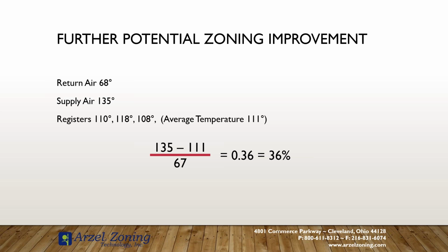And it seemed like such a simple thing to me that it really ties in well with zoning, because when we look at how zoning increases the velocity, that velocity changes our duct BTU loss because it spends less time in contact with the ductwork. Now, if we've got significant enough duct leakage, then we need to correct that, and that'll drive our number down further. But optimum velocity, duct sealing, air balancing, that's going to give us the best BTU delivery and the best comfort for our customers. The trick really comes into identifying which